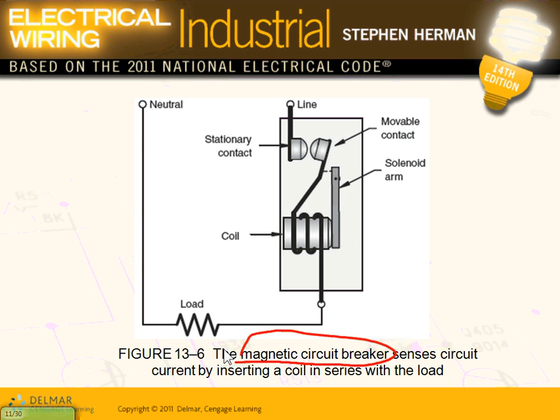So you have, Ashley, we sent her to work somewhere, and she shorted this system to ground. I have a short circuit. Now, this is a 20 amp circuit breaker, the same 20 amp circuit breaker that we looked at. Now I have a ground fault of 1000 amp. I shorted phase A to the ground. Okay, now this 1000 amp will create what?